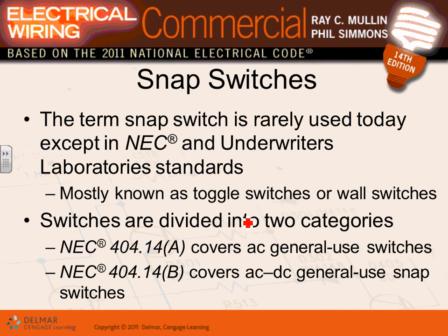And almost all the receptacles that we use in a commercial building are 20 amp, 120 volt. You wouldn't use 15 amp, though there are a lot of 15 amps. I didn't say you wouldn't by code, but it's a good idea to put in 20 amp receptacles.